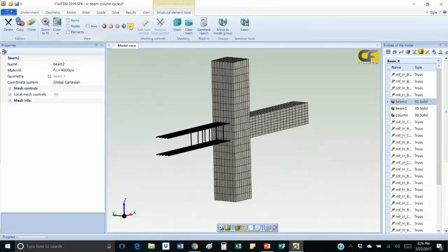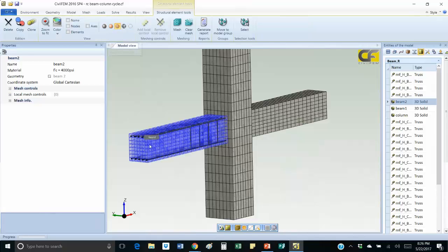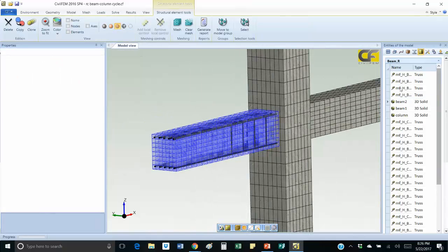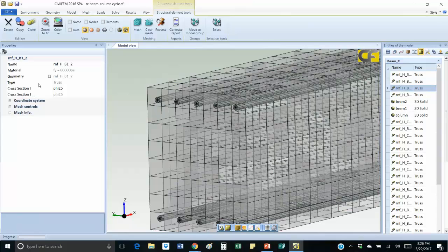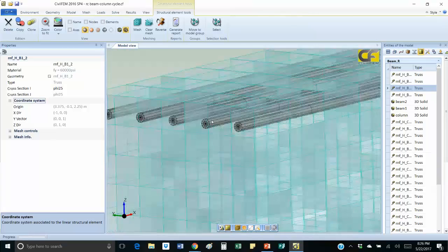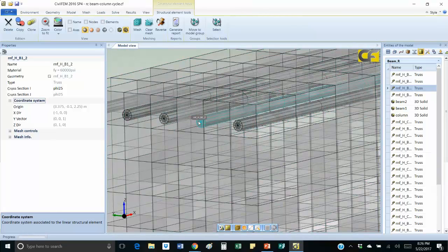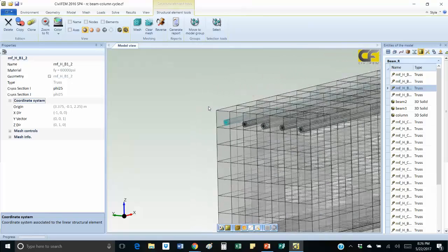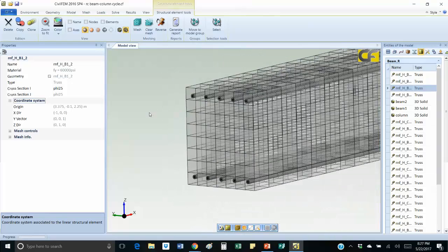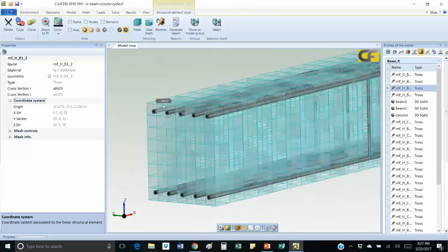And we have the inserted elements, which in this case are the reinforcing bars, and with only 2 or 3 clicks we define touching one element and applying it to another element, we simulate a real behavior. So we can reduce the work to only drawing and assigning properties, and CivilFEM is in charge of all the hard work of connecting, meshing, gluing, and all of those things that in other software are sometimes very uncomfortable for simulating.